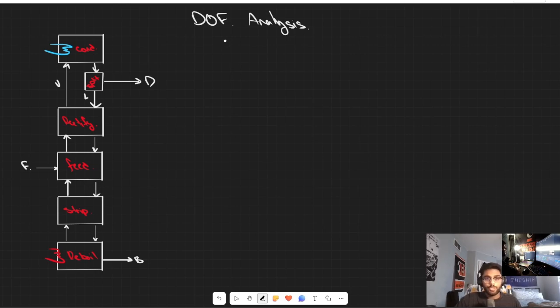So our goal here is to do something called a degree of freedom analysis. We're going to take each stage listed here in our distillation column setup, and determine, using an analysis of the variables and the equations involved, the minimum amount of specification that we need to provide in order to run this distillation column effectively. So we will do this stage-wise.